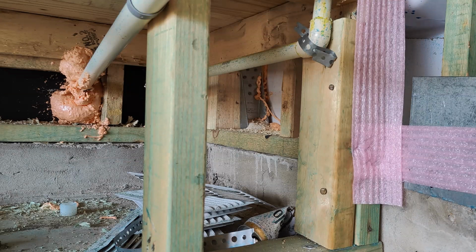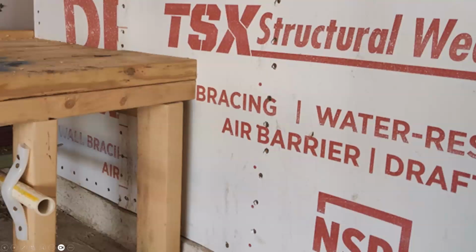Here's the water heater platform that's on the garage wall. Same kind of thing here. It's a structure built in front of an insulated wall that would normally be covered by an air barrier like sheetrock. It's just another platform being built out. But since it's being built before sheetrock, there's not a complete air barrier behind the water heater decking. So code now requires this to be completed by blocking, sealing, and insulating completely underneath and behind these water heater platforms. So it must be sealed off like this.